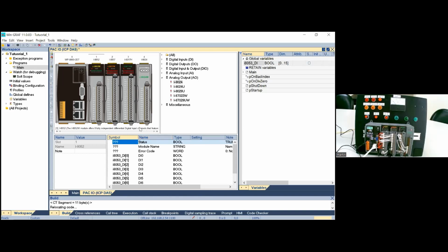The same procedure we will repeat with the digital output module. We create a new variable, an array again. It's a digital output. Just enter. Again, digital output, data type is bool. This module has 16 channels. We create an array with 16 elements. And in addition,